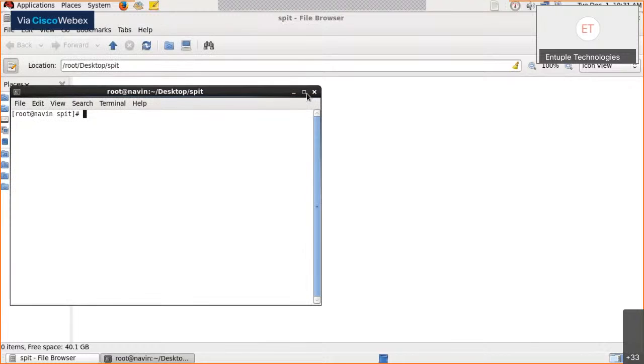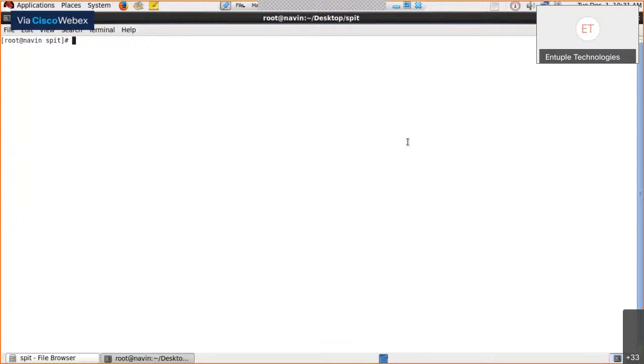Now what happens is I'll initialize the shell script, because the operating system, Red Hat Enterprise Linux, and Cadence have certain libraries in common. So they are mapped with the help of a shell script. We are initializing the shell script, and now let us source the CSHRC file. CSHRC stands for C shell run command, which has the location of the tool installation directory. The CSHRC file contains the location of tool installation, wherever your tool is installed on the particular machine.